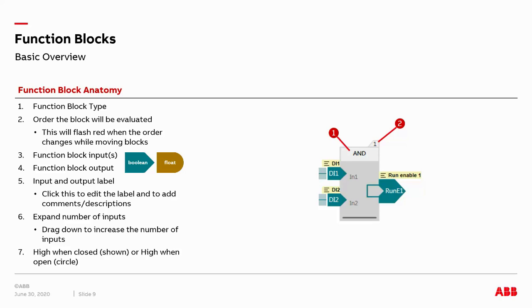There are some instances where if you place the blocks in a certain way on the screen, you can actually have the order get all jumbled on how it evaluates things. Instead of being sequential, it kind of just bounces all over your adaptive program. So just be mindful of your order. You could end up in a space where you try to do calculations on something that had a dependent before that never ran its calculation yet. So be wary of that. Watch those orders, how everything's going to be evaluated, and move things around accordingly.